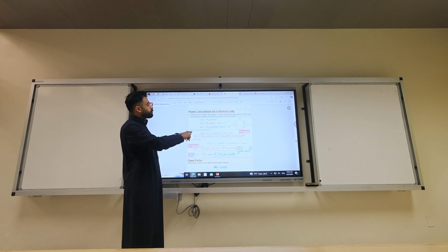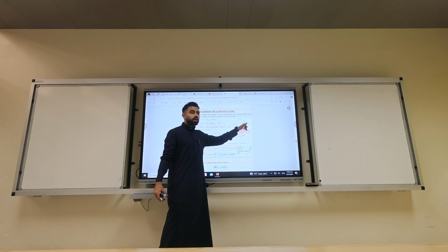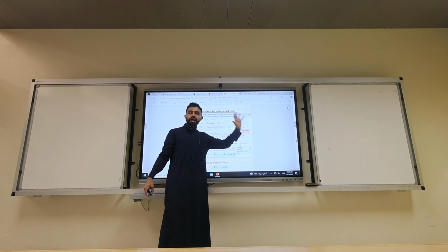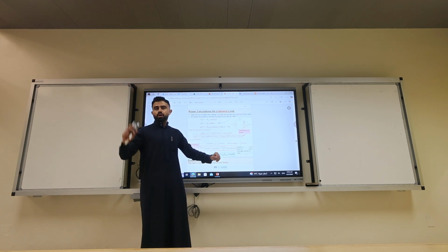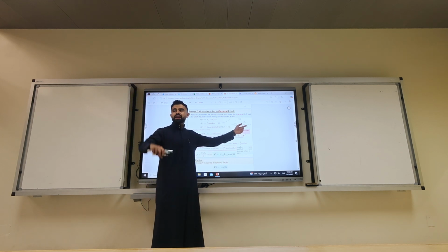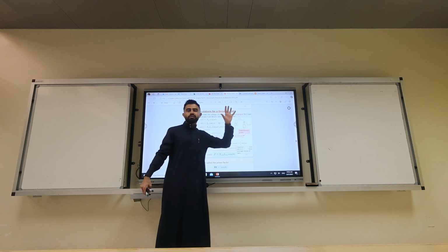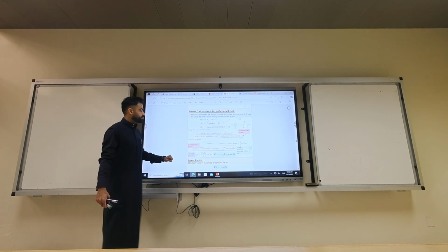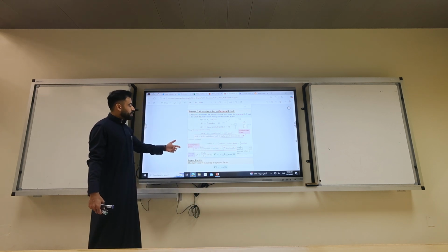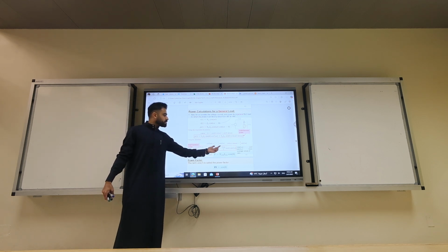Then we said, what if we have a general load? We'll have R plus jX, where X can be either omega L or minus 1 over omega C. If it's minus 1 over omega C times j, or 1 over j times omega C, that's going to be a capacitor. The generic formula, after we did the derivation, comes into three different terms.